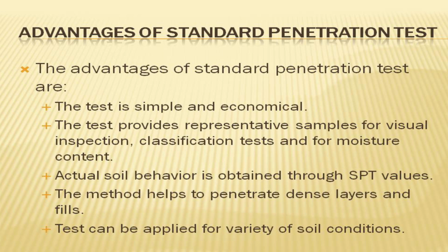Advantages of standard penetration test. The advantages of standard penetration test are: the test is simple and economical. The test provides representative samples for visual inspection, classification tests, and for moisture content. Actual soil behavior is obtained through standard penetration test values. The method helps to penetrate dense layers and fills. Test can be applied for a variety of soil conditions.